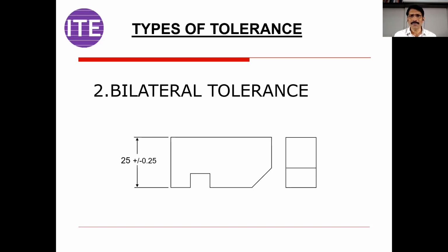But it doesn't mean that there is no tolerance value on the hole. There is a tolerance value. But in the case of the hole basis system, you must have observed that the first value of that tolerance is 0.000. So providing the tolerance is not that important. What is the most important factor here? What type of fit you are going to achieve?